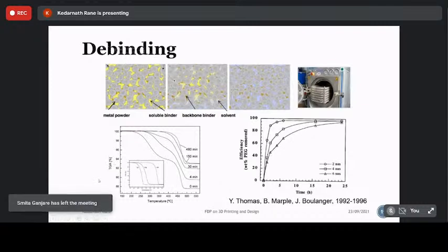Again, in this picture, you want to consider that to understand the melting of the polymer, you can go for TGA analysis. You do TGA, and you can have a clear picture of how much time it takes to remove the complete binder at different temperature conditions, like PP, paraffin wax, stearic acid. Different binder constituents require different hold times and temperatures to remove the constituents.